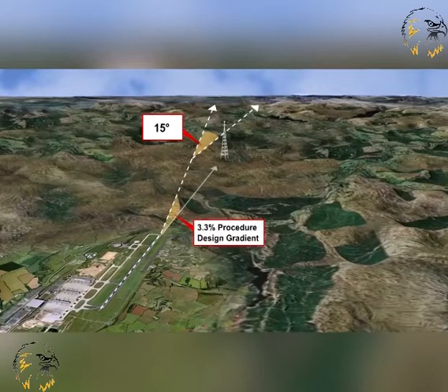Departure procedures will be established for each runway to be used, and will define the procedures to be used for each category of aeroplane based upon an all-engines running procedure design gradient, PDG, of 3.3%, to achieve minimum obstacle clearance.